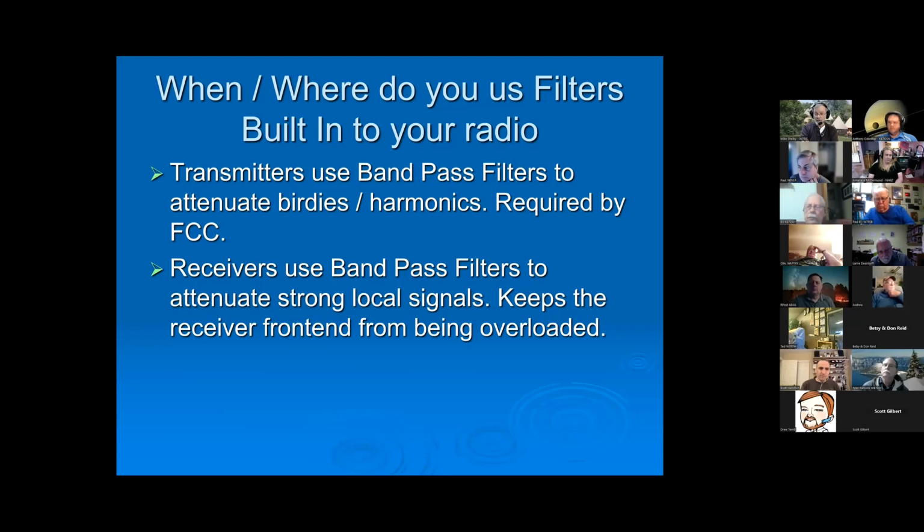Very typical, your transmitters make little birdies and little harmonics, and not all of that can get cleaned up, especially if you're in a close area. So typically you'll have bandpass filters in there for each band that you're operating in to clean up all the dirty RF that is being created by your transmitter.